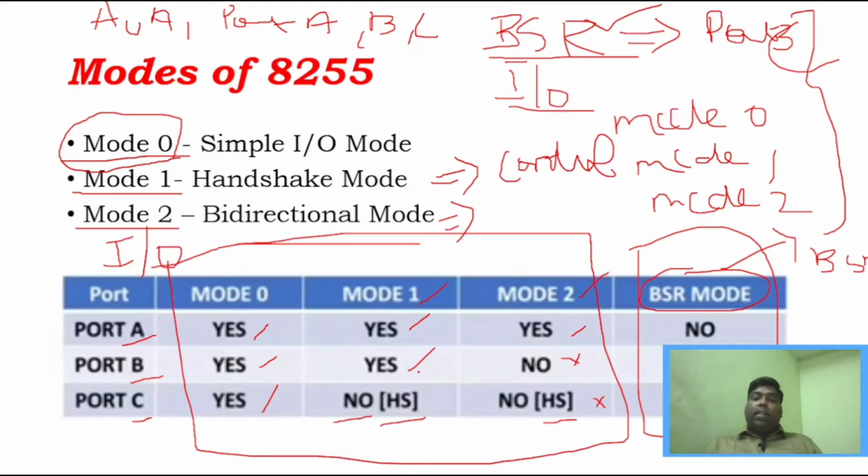Say for example, if port A as well as port B of the device are both involved in data transfer, then port C will support the handshaking process for port A as well as the handshaking process of port B, right? That is, 4 bits will support port A and 4 bits of port C will support port B